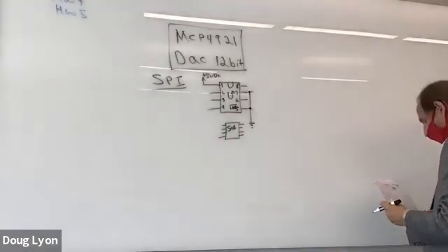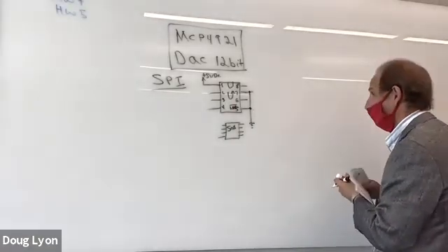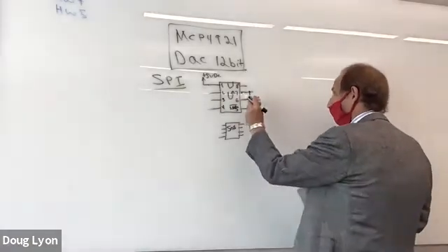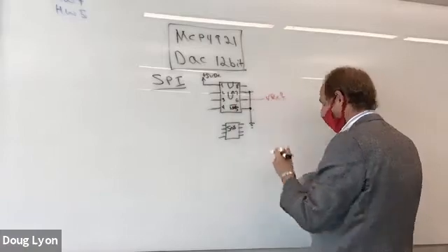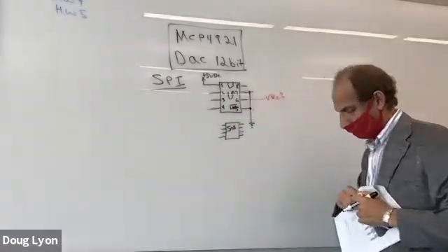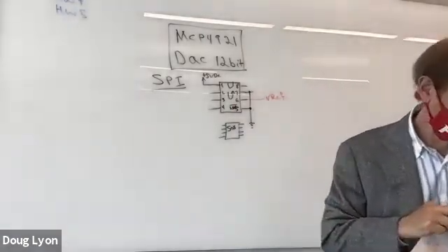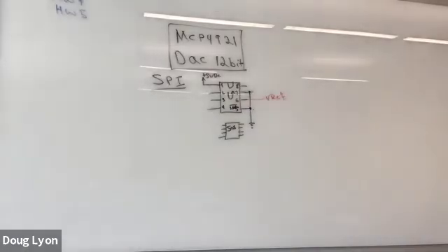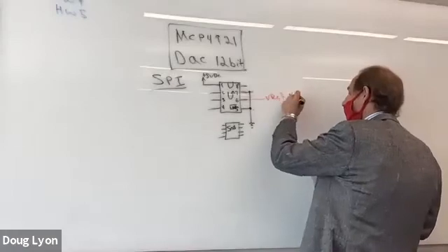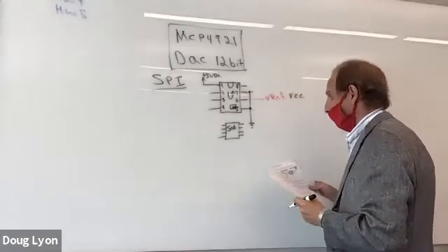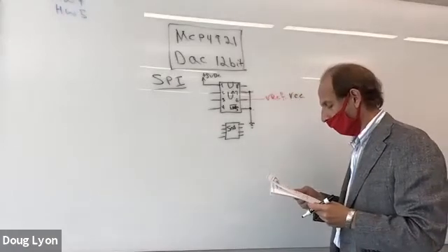What we'll do is you can use an outside, external voltage reference, if you like. In other words, the DAC can be floating around 0 volts and go plus or minus 1 volt, if that's what floats your boat. But if you put it out to VCC, what will happen is the DAC will go from 0 to 5 volts, which is just fine.